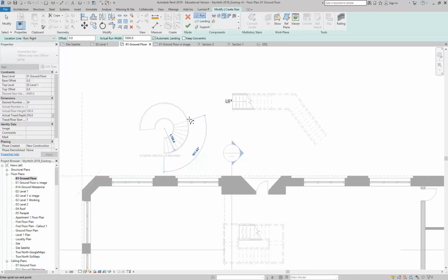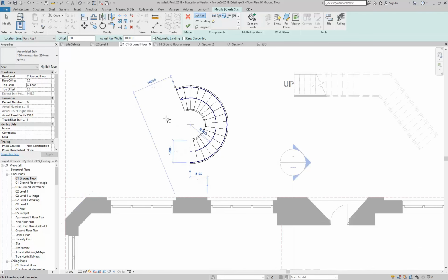But again, it's just like the other stair. We can only have 18 risers before we need a landing. And because we need a landing, and I know we do, then it doesn't have to be at 18 where you have the landing, it could be at 12. So you can always check that. But I'll make it 18 this time, just something different. So there we are, so 18. And then you'll see it'll tell me I need another 6. So how do I start my next flight?